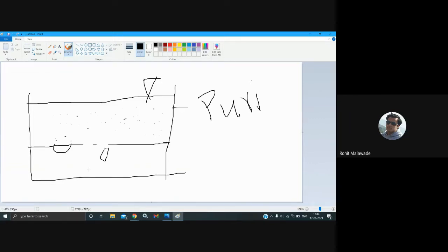If we don't remove them, even after sediment coagulation or sedimentation, we will be left with these fine suspended particles which have not been removed by your coagulation sedimentation. Here we are going to remove them with the help of filters.